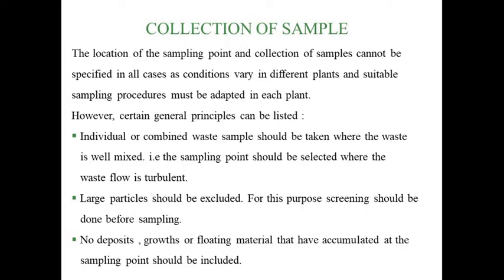Individual or combined waste samples should be taken where the waste is well mixed. That is, the sampling point should be selected where the water flow is turbulent. Large particles should be excluded, and for this purpose cleaning should be done before the sampling. Next, no deposits, growth, or floating material that have accumulated at the sampling point should be included.